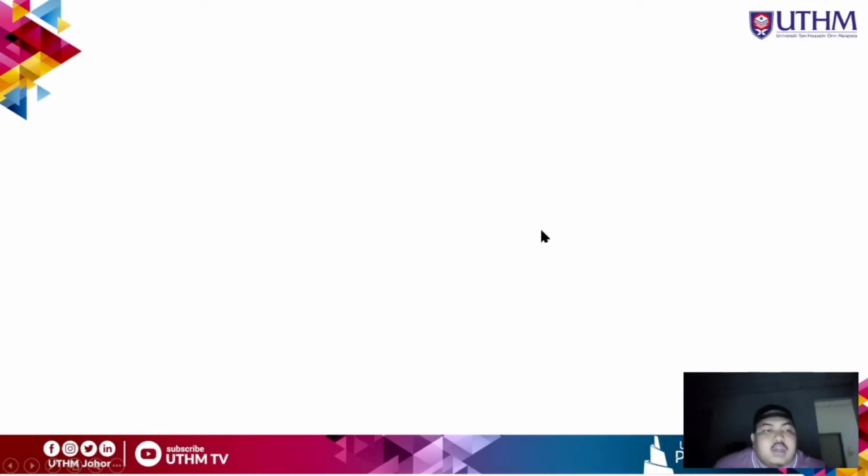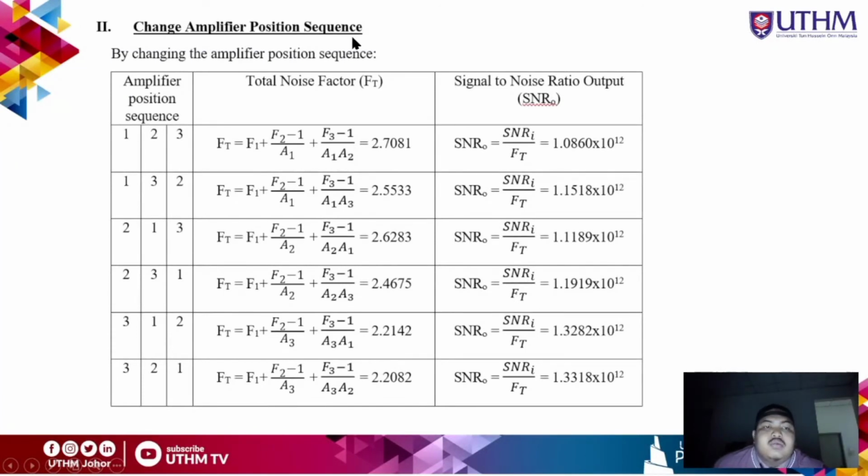Okay, next we move to the second method, in which we change the amplifier position sequence. By changing the amplifier position sequence here, we can get the total noise factor, and then we can calculate the SNR output for each sequence. As we can see, the highest SNR output is the last one, where we put the sequence from amplifier 3 to amplifier 2, and last amplifier 1. We get the SNR output equal to 1.3318 multiplied by 10 to the power of 12, unitless.